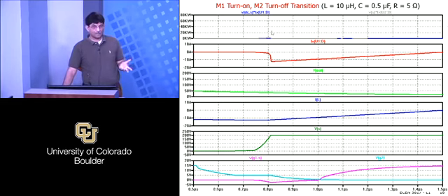The problem is gone. The good thing now is that even though in that earlier transition you've put energy in those capacitors, now because the current is negative, it's actually discharging those capacitors and not wasting that energy in the channel of the MOSFET. It's either supplying that energy back into the source, or it is just part of the output current, right? Either way, this transition is really nice, right? The M1 turn on transition. But the essential thing again is the current was negative at that transition, the inductor current.